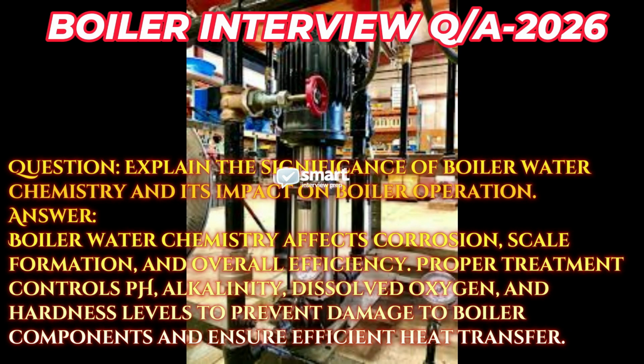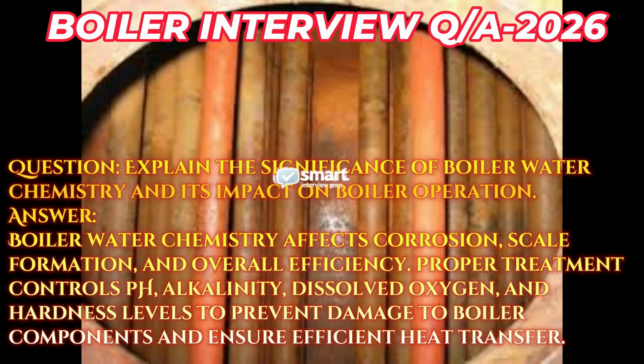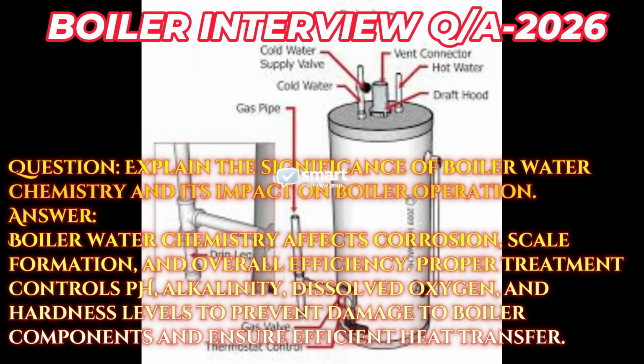Question: explain the significance of boiler water chemistry and its impact on boiler operation. Answer: boiler water chemistry affects corrosion, scale formation, and overall efficiency. Proper treatment controls pH, alkalinity, dissolved oxygen, and hardness levels to prevent damage to boiler components and ensure efficient heat transfer.